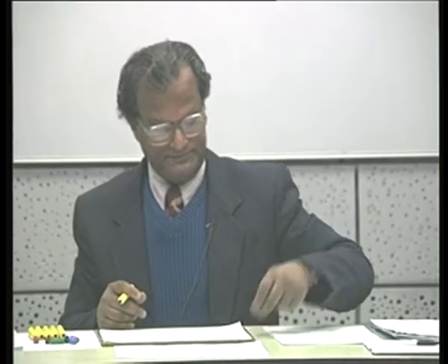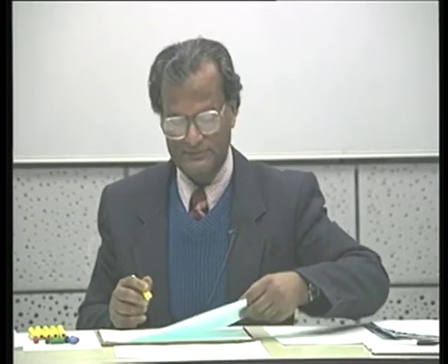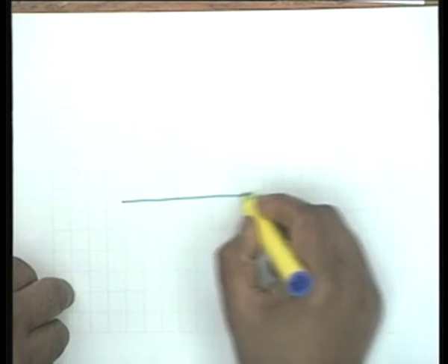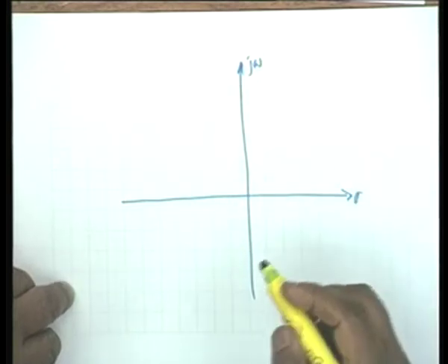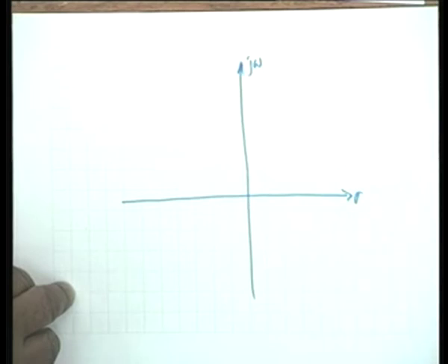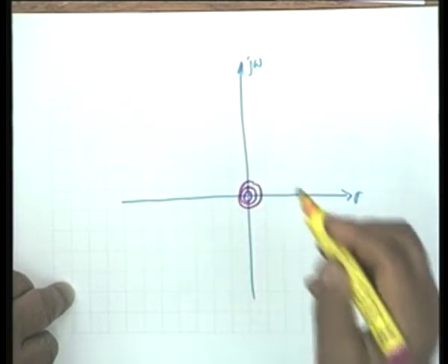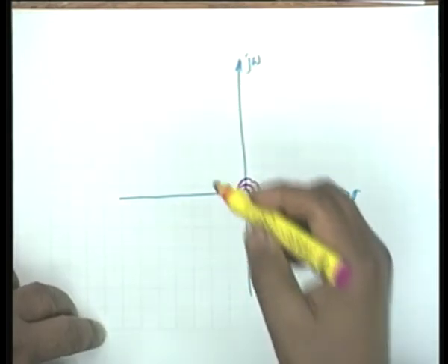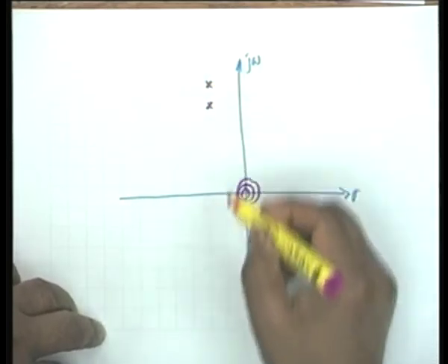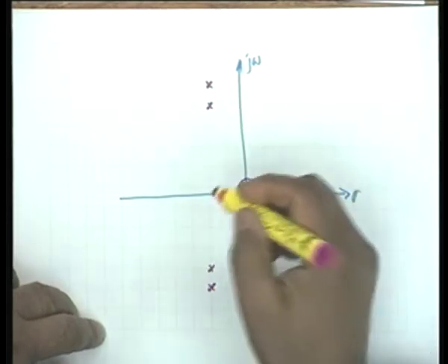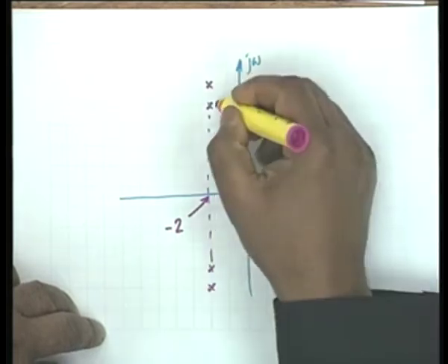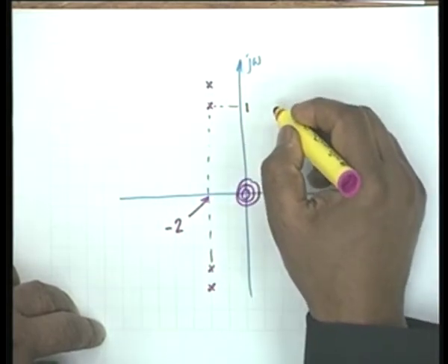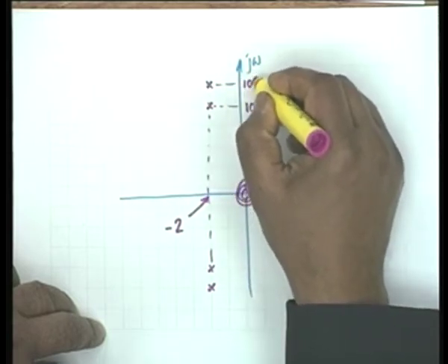And if we look at the pole zero diagram, there are 3 zeros at the origin as in the tuned circuit, and if we exaggerate a little and distort the scale a little, there are poles here and here, where this distance is minus 2, this is 100, and this is 106.